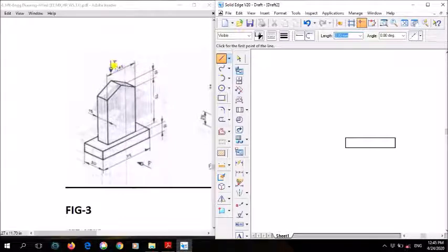30 mm, right? So there is a gap of 15 mm this side, and a gap of 15 mm this side, right? So you have a gap of 15 mm this side, and a gap of 15 mm this side. So what you can do is, now using thick line only, from this end, from this corner, mark a point at 15 mm. From this end mark a point of how much? 15 mm.